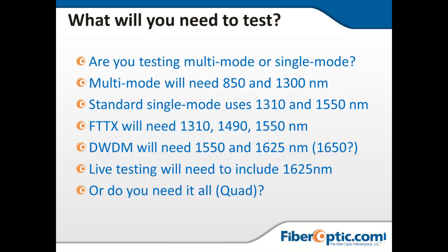So the first example of that will be the fiber to the home, FTTX application, where we'll sometimes see this 1490 wavelength come into play. That 1490 is actually the transport signal for the internet as it comes down from the head end. So our Ethernet traffic is going to come down to our NID at that 1490.